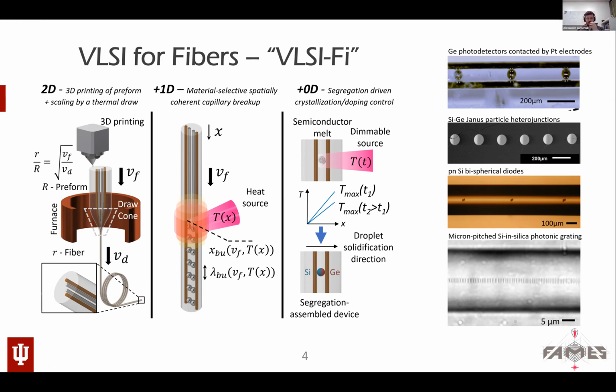So you can design the distances between initial continuous cores such that those droplets, when they detach from the continuous cores, they will touch each other and electrodes on the side. And you end up with an array of p-n junctions contacted in parallel. So that would result in an array of photodiodes contacted in parallel by 2 metallic electrodes.